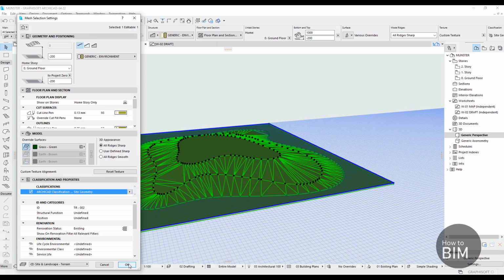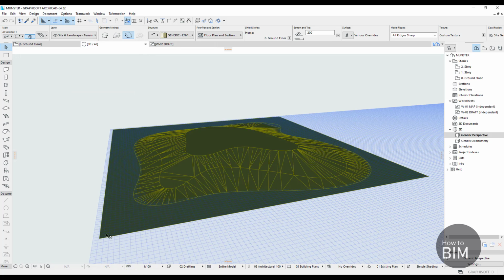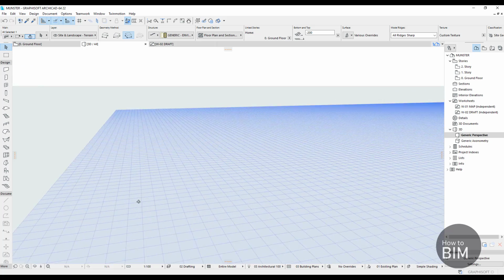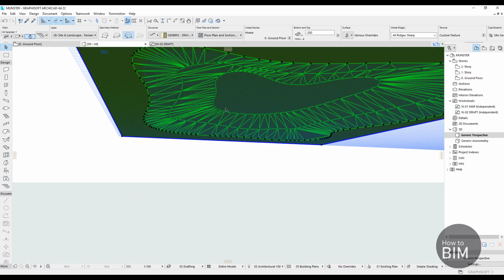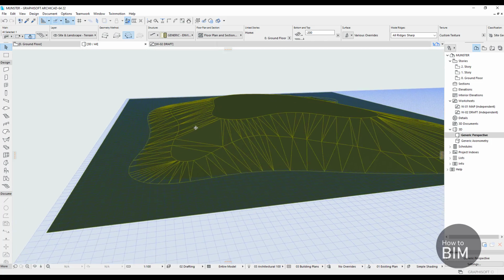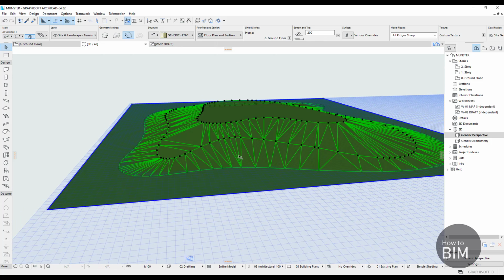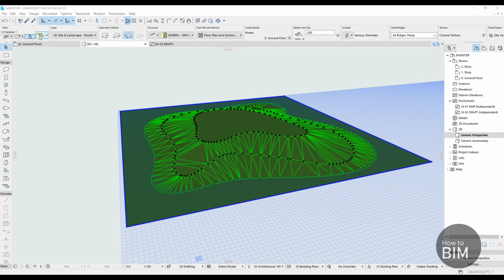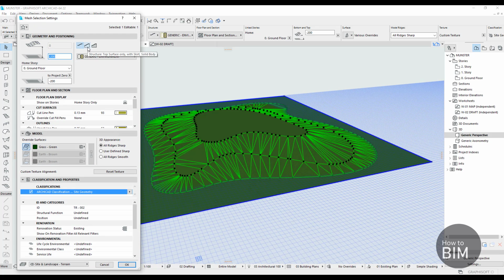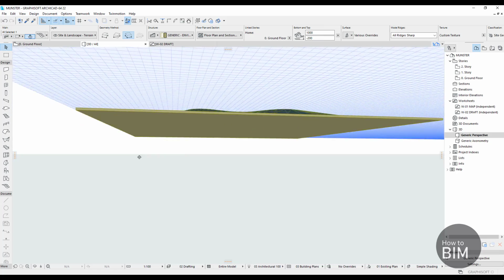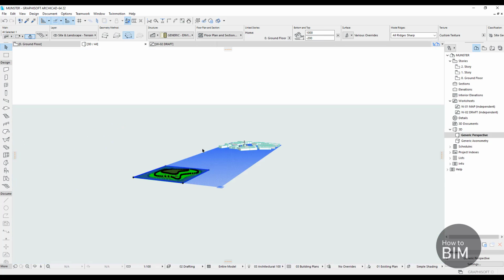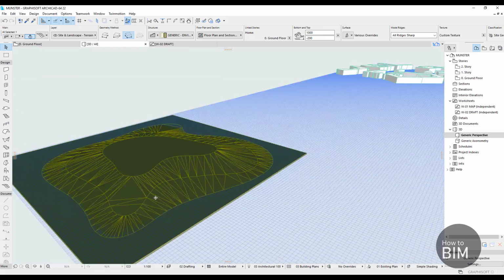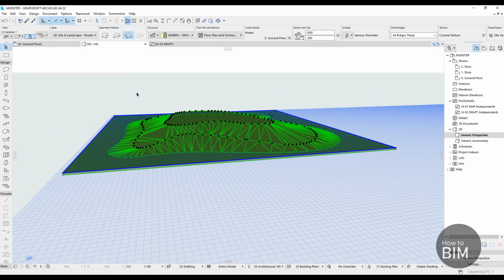If you want only the top structure, you can click on this, and now as you can see it's empty. So that means that we have only the outline. It works like a shell with 0 thickness. Then you have this option, this was the solid body. So that means that if you cut through, it will be filled inside.